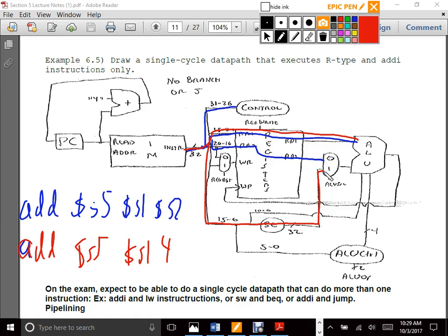So I do require ALU source because I need to make that decision. So you have 0 or 1. 0 is the input from read data 2, and 1 is the value of the sign extended value. For add, I also need the function value. I need 5 to 0 to be sent to the ALU control. I have that 2-bit ALU op every time. Also, it is an R-type. So for R-type instructions, I also require 10 to 6 because of shift left logical.